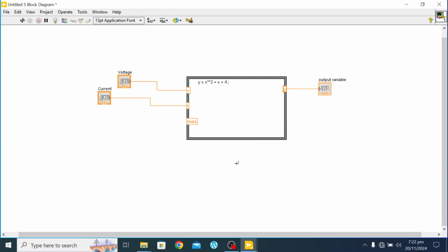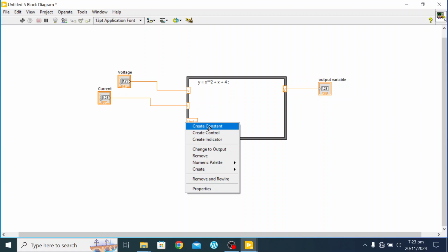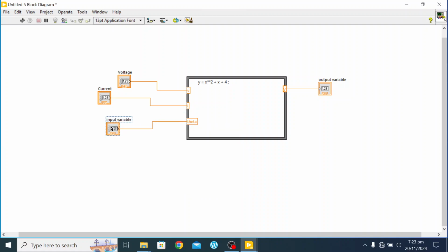But in LabVIEW, when you give an angle to trigonometric functions, it considers it in radians. We have to change it. The value we are going to type will be in degrees, so we'll have to change those to radians, assuming we are taking a control here. Have to just cut it here, delete. This cross sign, how would you diminish it? Just control B it. It's done.